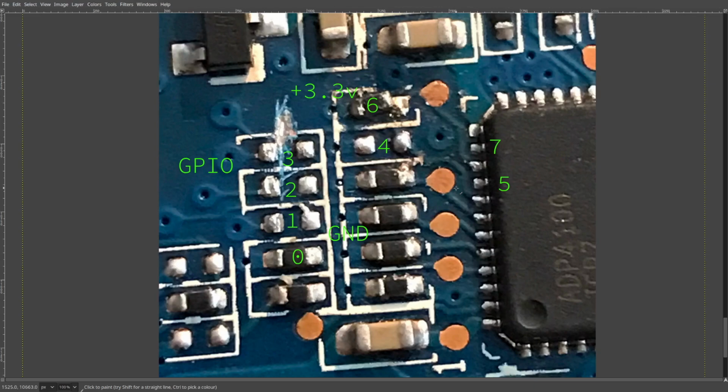And you could technically set it to 1.4 and go down, because you get a bit more range going down from your under voltage protection. But then you're also going to have a lot of droop. So ideally, you set up your feedback mod such that you do that, but then that would mess with your compensation loop. It just gets complicated. So ideally, if you can solder to this, it is difficult, but doable.